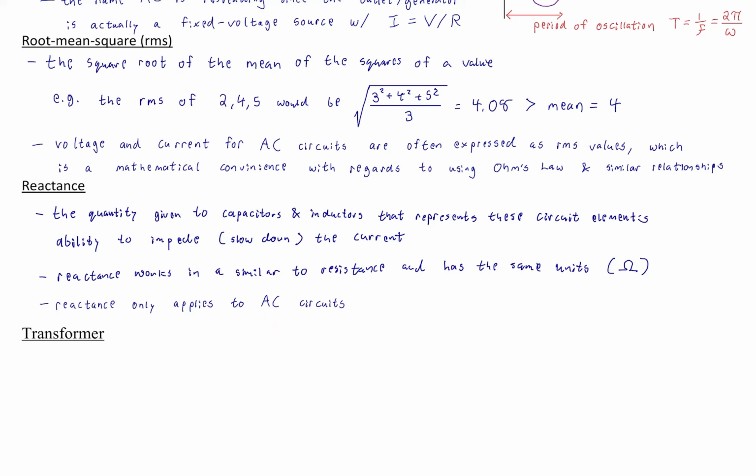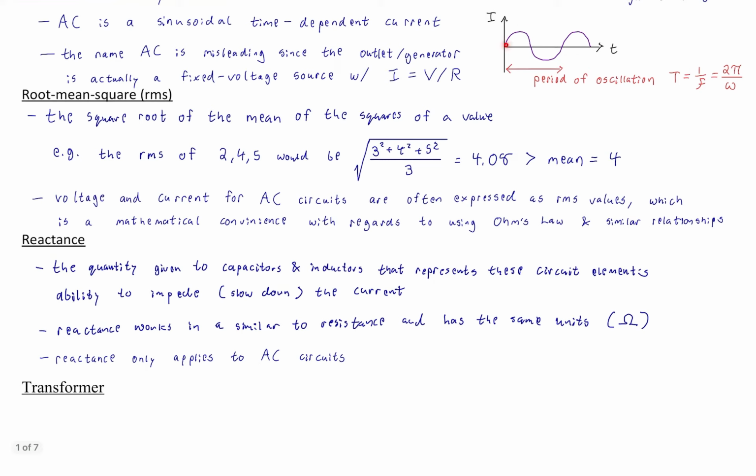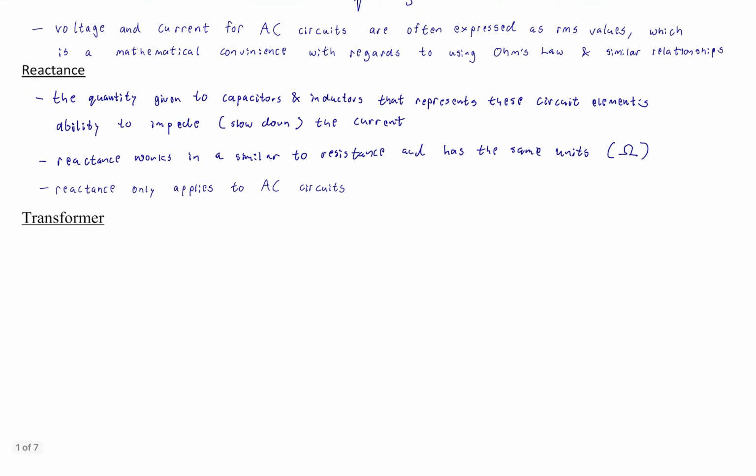That's why we've never mentioned it before, because in a DC circuit, as we know, you charge a capacitor and it's done. But in a current or a voltage source that's going up and down, the capacitor is constantly being charged and discharged. So then it actually affects the current over time because a capacitor that takes a long time to charge and discharge is going to have a greater effect on the current than a capacitor that quickly charges and discharges. That's the idea of relative impedance, which is expressed as reactance, relative reactance showing up in Ohm's law, measured in ohms. Okay. Right, and obviously we'll show the equation that allows us to take the units of, say, a capacitance over to ohms, all right, or inductance over to ohms.